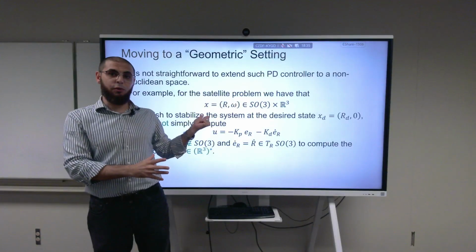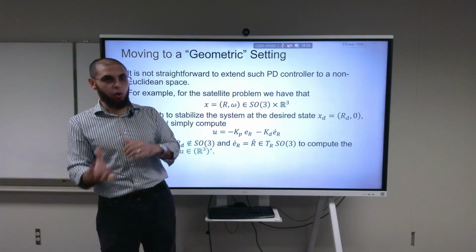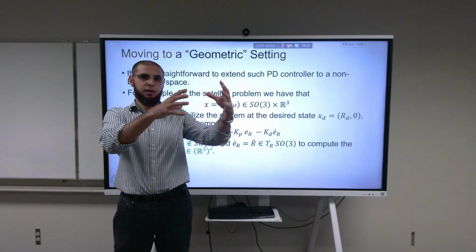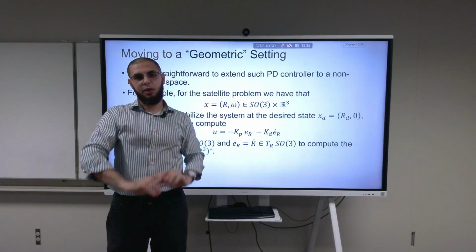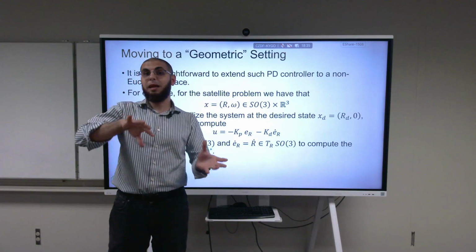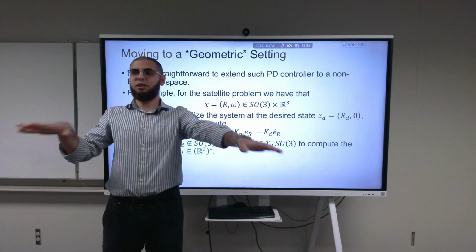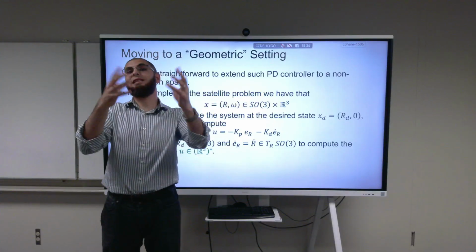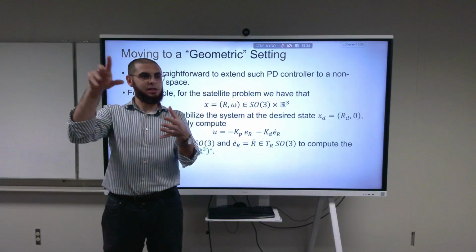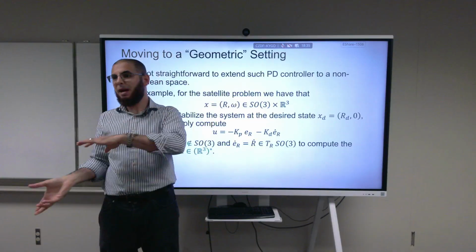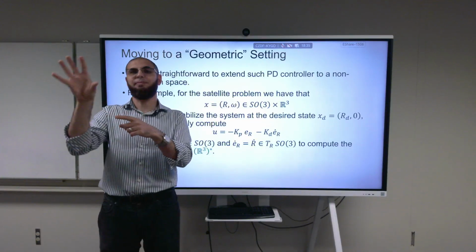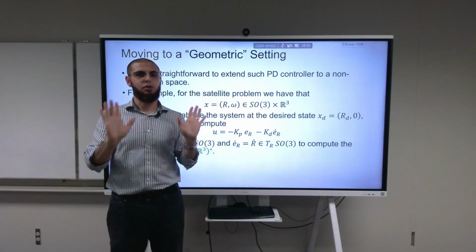Now, usually how we do the control here is that you control the UAV as just a single rigid body, and then you take the wrench that you have and you invert it. Sometimes the map is easy. All of the projects that you have had an easy invertible map because you have a fully actuated UAV, which means that the map from the wrenches to the individual propellers is just a 6x6 matrix, and it's invertible, so that's easy to do.